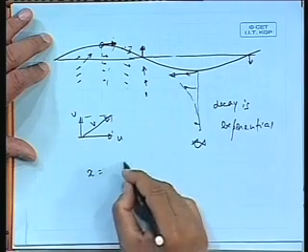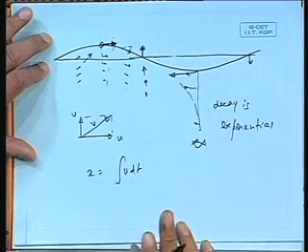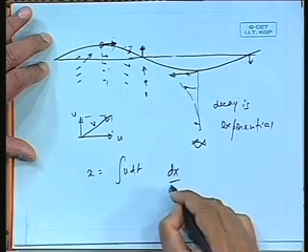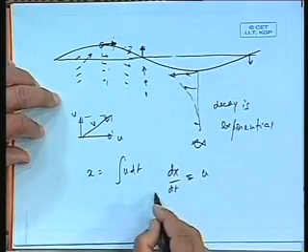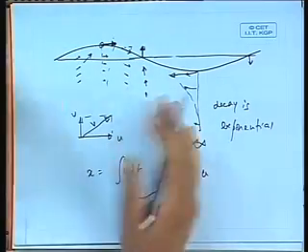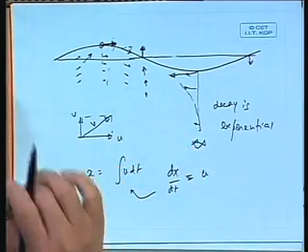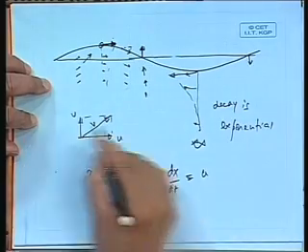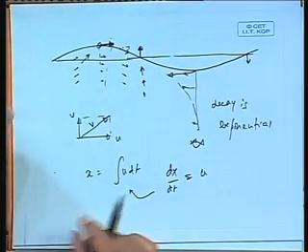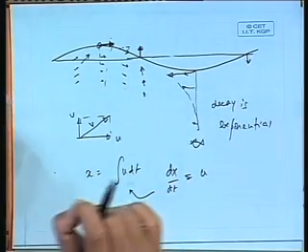Now this is what we call the particle velocity. Now you see, if you know particle velocity, you can also find the trajectory, because the x distance is nothing but the particle velocity integrated. After all, dx by dt gives you u. Therefore, you can get to this. So there is a way to find out, if a particle started from here, which direction it moves. It is called trajectory. That is more illustrative because you want to know how the particles are moving.